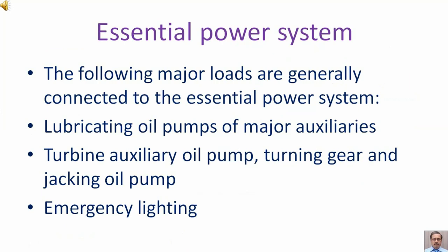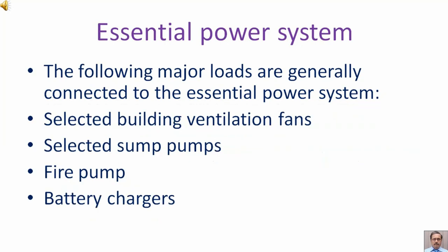The following major loads are generally connected to the essential power system. Lubricating oil pumps of major auxiliaries, turbine auxiliary oil pump, turning gear and jacking oil pump, emergency lighting. Selected building ventilation fans, selected sump pumps, fire pumps, battery chargers.